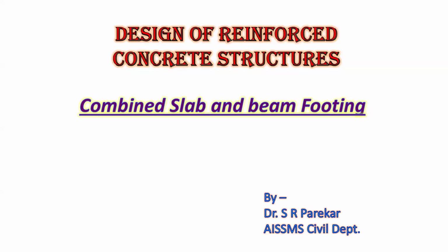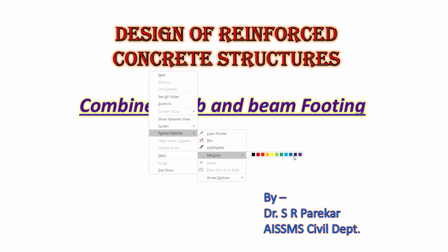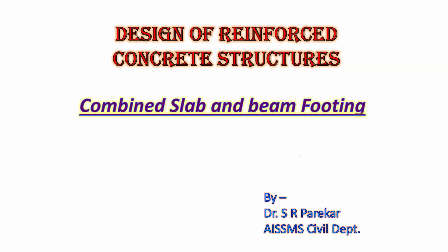Good evening. We have this video on combined and beam type footing. Before this, we dealt with axial load and uniaxial moment. Now, when the load on the column is greater, we will go for combined slab and beam footing, because in that case the depth required for the slab is more, and to provide an economical footing, we go for this.